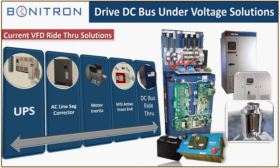For example, in the United States, most of the specifications we see are just a partial AC line loss or sags, and it could be one phase and the other two phases remaining or degraded. But as long as we have 60% remaining, then we'll back it up with the DC bus ride through. Some of the other solutions out there are UPSs, AC line sag correctors, and then also in some applications you have motor inertia too. Not all. Pumps, no inertia there, but fans, you do have inertia there, for example.